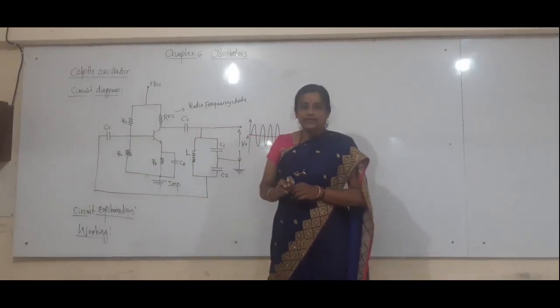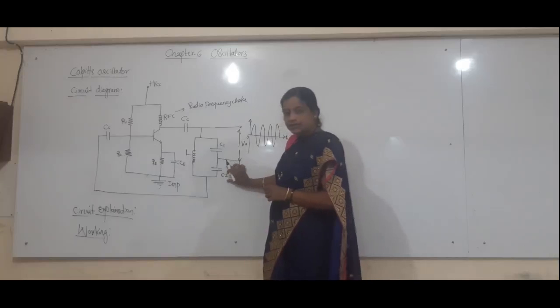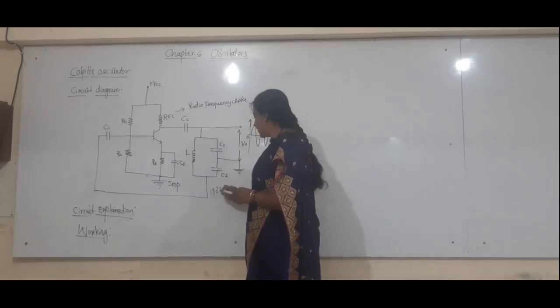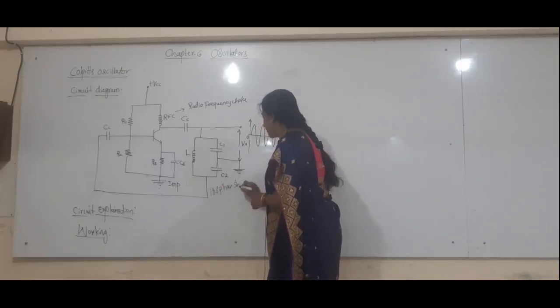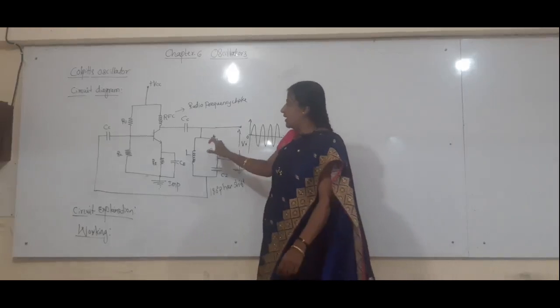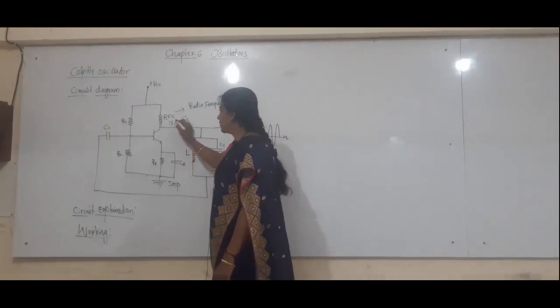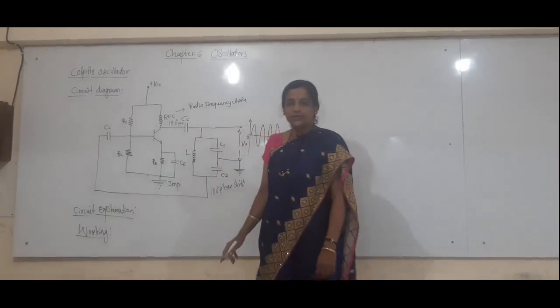of the amplifier circuit. This voltage drop across C2 is such that it produces a phase shift of 180 degrees in the feedback signal. That 180 degree phase shift is introduced by the potential across C2, as well as one more 180 degree phase shift produced by the voltage divider biasing circuit, that is, the amplifier, which also produces a 180 degree phase shift.